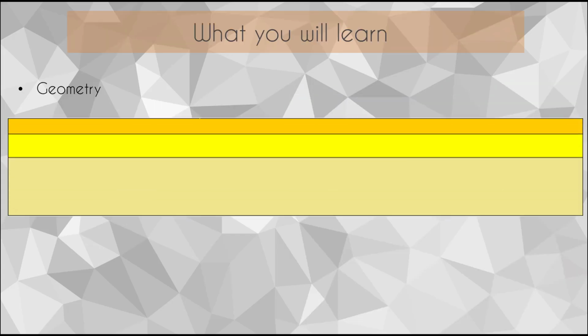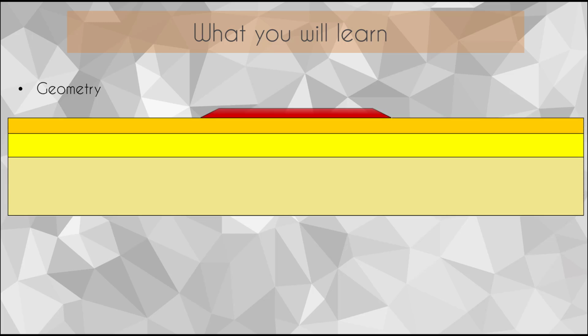What you will learn: we start with the geometry. Initially, we have a soil with 3 saturated layers, then we model the embankment. For simplification reasons, the geometry of the embankment is symmetric, so the model can be reduced to 1/2. In addition, the embankment is modeled by a trapezoidal pressure distributed in a downward direction with respect to the variation of embankment thickness. Moreover, taking into account the length of the embankment compared to its area section, the model can be analyzed in plane strain.